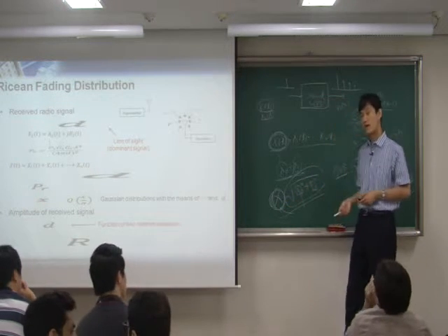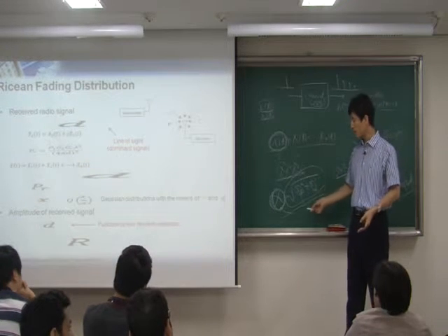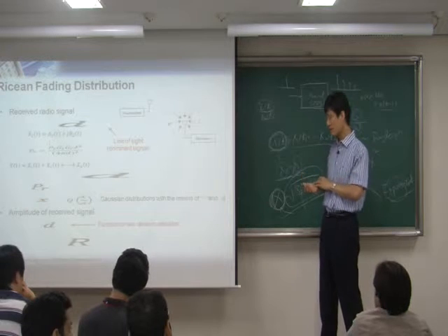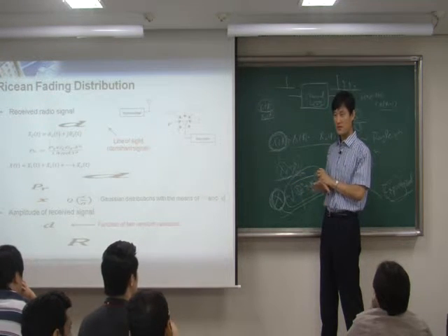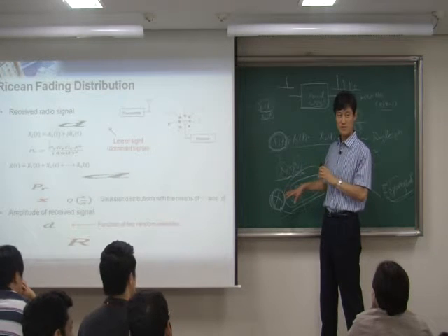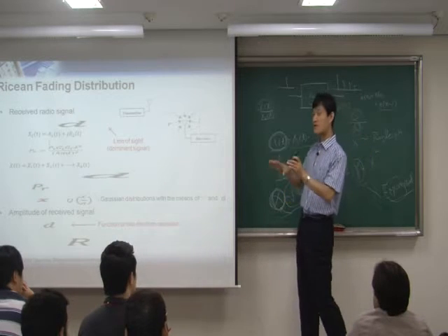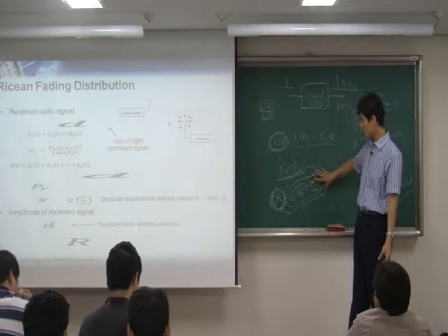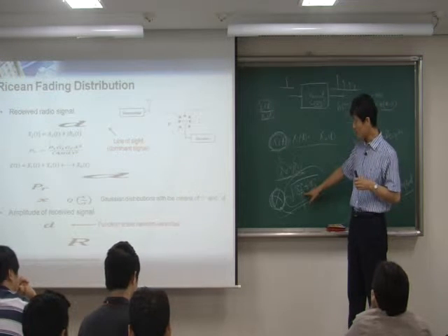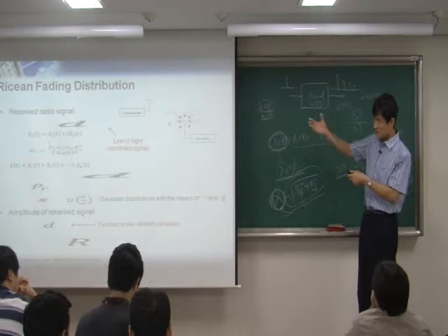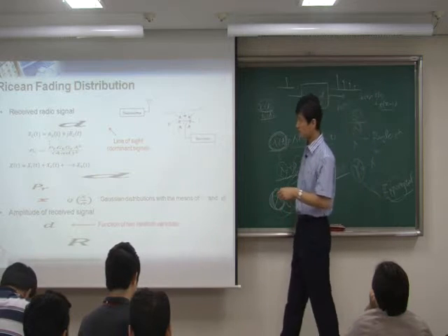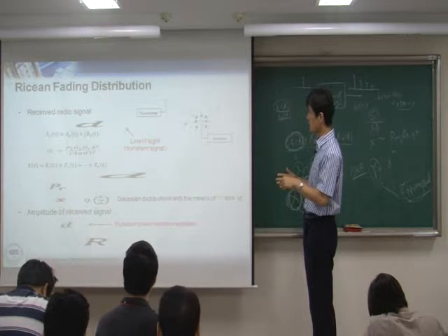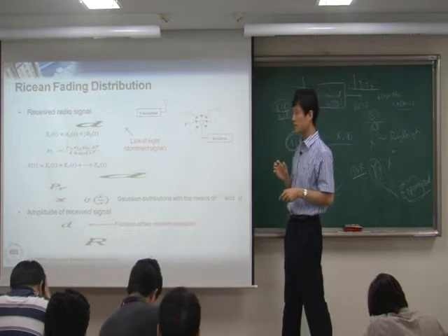In fact, solving this one is very complex. In the earlier case, with zero mean Gaussian, finding the Rayleigh distribution is pretty simple. Some of you remember that, right? I used this one as one of the problems in the midterm. I just give you a warning, I might do that again. But that was the Rayleigh case. It's as simple as that. You can solve it right away, even in the midterm. But in the Rician case, it's very difficult. The only difference is that this is a non-zero mean Gaussian, but it's very complex. So we'll just refer to the result. This one follows a Rician distribution. So the difference compared to Rayleigh fading is that you think about an environment where a line of sight path is there. That's the only difference.